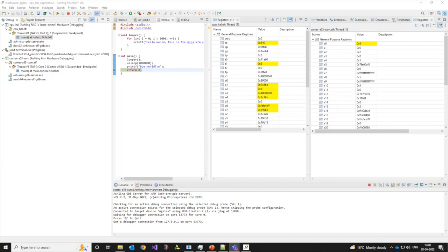Here's another question that came up during registration: what are the differences between Nios V and Nios 2? From the software perspective, Nios V does not require Windows Subsystem for Linux and uses CMake for building applications, which Nios 2 did not use.